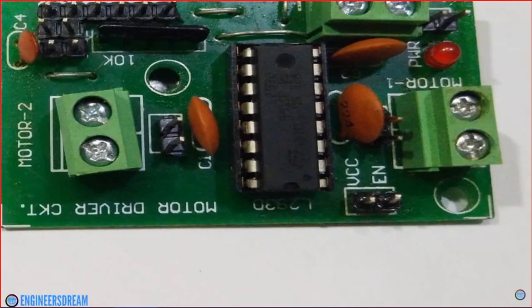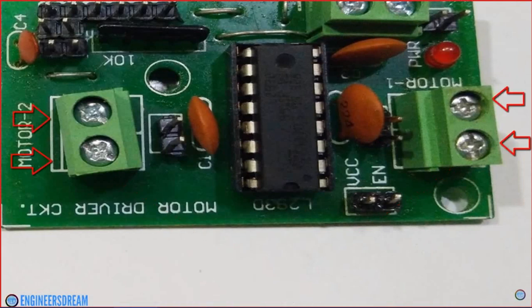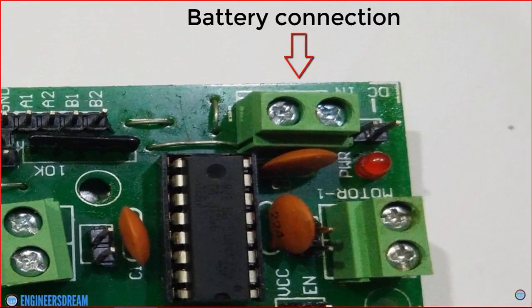The 2 green sockets at the bottom are for connection to the DC motors. So, the output pins of the motor driver IC, that is pin number 3, 6, 11 and 14, can be accessed from these green sockets. Each socket consists of 2 holes in which we have to insert the DC motor wires. And you can also see the green socket on the right hand side is used to supply external power to the motor driver using a battery.